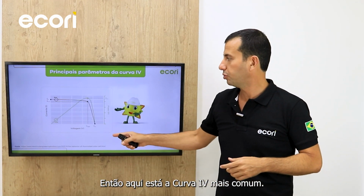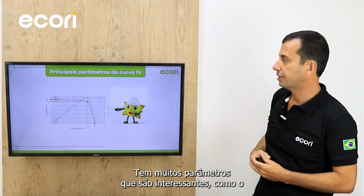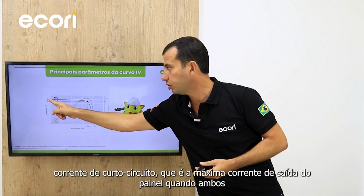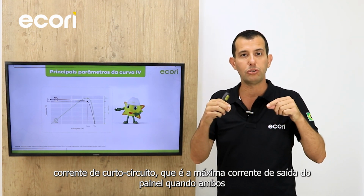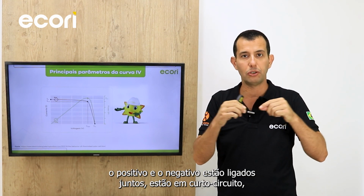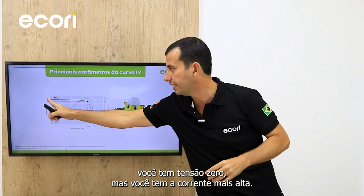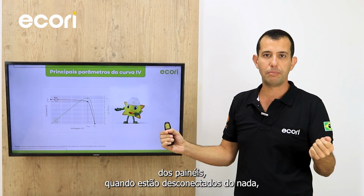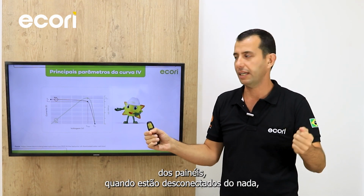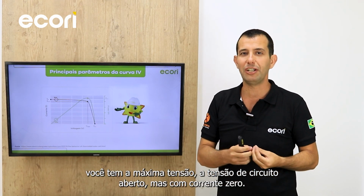So here is the more common IV curve, as you've probably seen, of a PV panel. It has a lot of parameters that are interesting, like the I short circuit, which is the maximum current out of the panel when both the plus and minus are connected together, are short circuited. You have zero voltage, but you have the highest current. And when you disconnect the plus and minus of the panel, when they are disconnected from everything, you have the maximum voltage, the V open circuit, but with zero current.